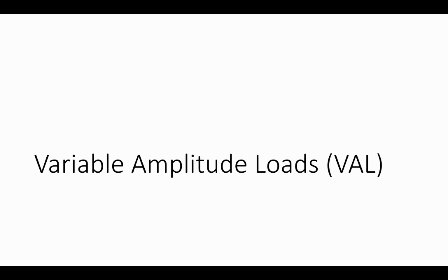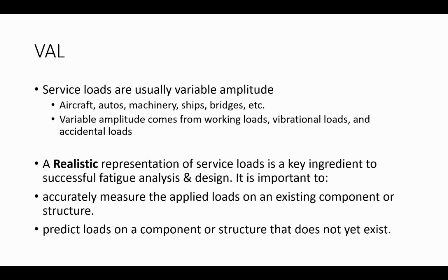Variable amplitude loads, VAL. Service loads are usually of a variable amplitude. This can include things such as aircrafts, automobiles, machinery, ships, bridges, etc., where the loads that are applied to those structures change with time, and they are not always repeatable.